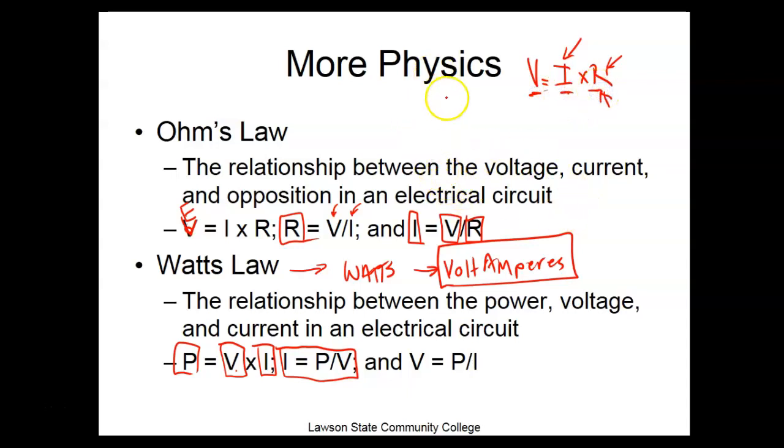But according to the power formula, I is equal to P over V. So Alabama Power is not trying to sell you current, and Alabama Power is not trying to sell you volts. It's even in their name, they're selling you power. So what that means is the higher I make this voltage, the less current that's going to be required to transmit that power. So if I was going to try to give you 1,000 watts of power at 1 volt, then it would take 1,000 amps.